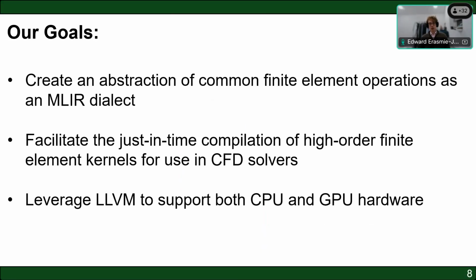So our goals with using MLIR are to create an abstraction of common finite element operations at the elemental level and implement them using an MLIR dialect. What we want to do really is facilitate the just-in-time compilation of high-order, in particular finite element, kernels for use in CFD solvers. And we really want to leverage LLVM and the JIT compilation to support both CPU and GPU hardware.